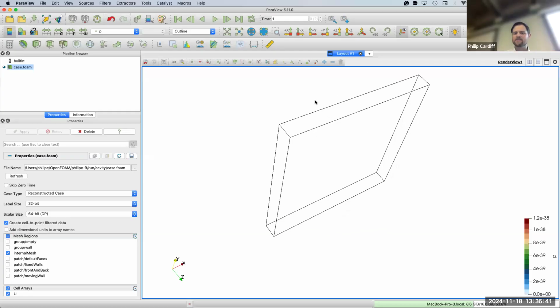So how you define these patches is, you give the 4 vertices of the block. So in this case, this moving wall. Just to remind you, we have vertex 0, 1, 2, 3. So 2, 3 is the top there. And then it goes 4, 5, 6, 7. So 6, 7. So 2, 3 at the back, and then 6, 7. They're the vertices.